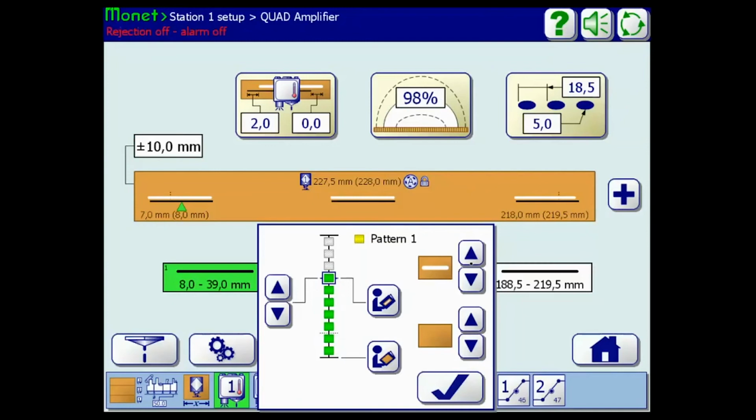So if there seems to be some variance amongst the focal distance of the hot melt sensors, it would be ideal to get them all uniform. Our assumption is they're still functional. They still work, but for continuity purposes, it's ideal to have them all set at the same focal distance.